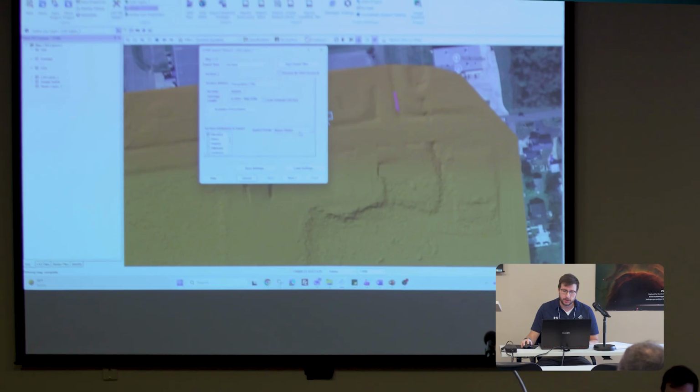We've been exporting GeoTIFFs the last couple of days, but there's a lot of other options here. The reason we do GeoTIFF typically is that most people want that format because that's what they need it to be in. But in a second, we'll do the same thing we've done the last couple of days: once we make the DEM in GeoTIFF format, we can use the DEM-to-LAS function to make a LAS layer based on that gridded DEM, and we'll have a gridded LAS data set. So that's another reason why we picked that option.